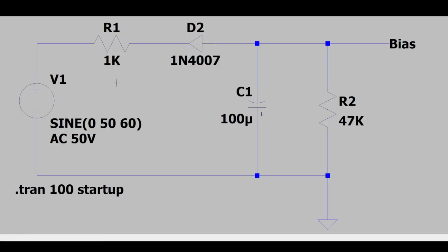Okay, so the next step I was going to take was going to be to build these circuits isolated on the workbench, build the stock circuit, powered up with my Variac at 50 volts AC, and measure the bias in DC volts on the output. However, I was getting much higher values here than I expected. Even with only 40 volts of AC applied at this point, I was getting close to negative 50 volts DC at our bias, and that was even after adding a 390K resistor between these 2 points to simulate the grid to cathode resistance of a single tube. So I think what we're going to have to do is instead look at these in the actual amp.